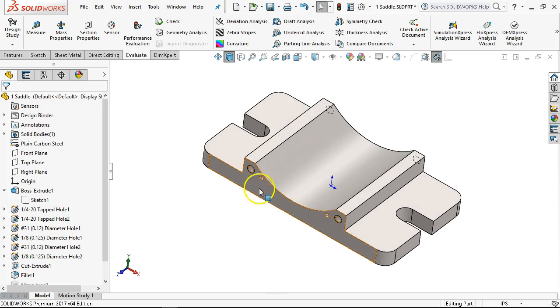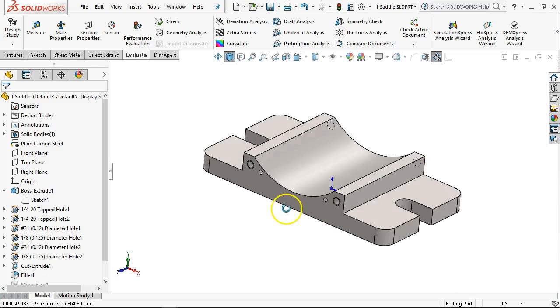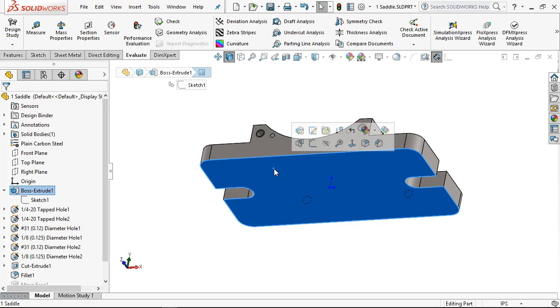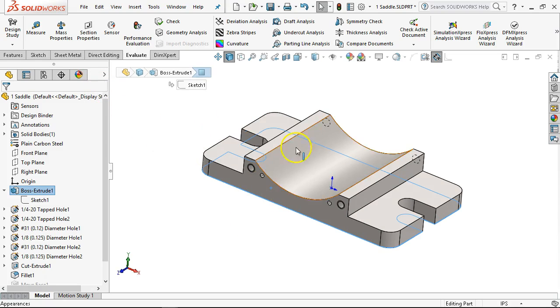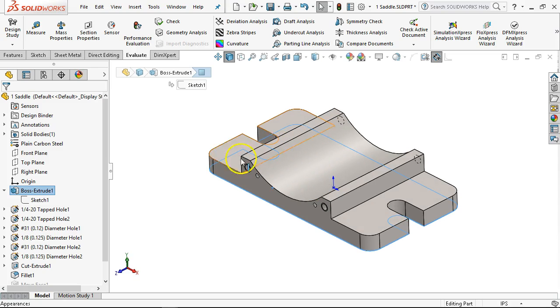And the plan is to not grind this face, because from a machining standpoint for that retainer, I'm going to be okay with the pin locations, so this can be a machined in-mill surface and satisfy the requirements. This surface I want flat. So when we come back to the drawing and do the GD&T portion, I want that to be flat. All right, and then the cylindricity of our arc.